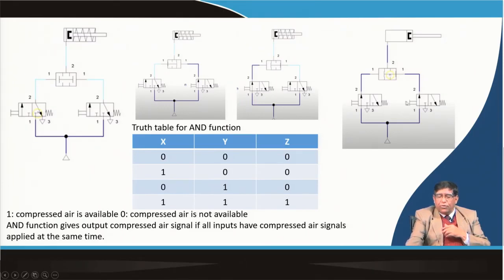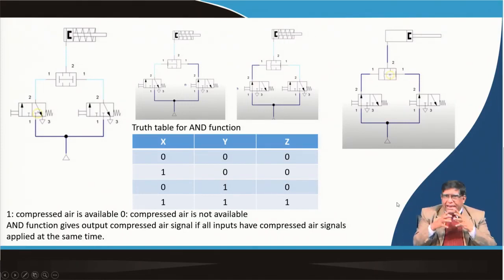But when the knobs of both these two valves are actuated or pressed, then you can get this air, and you can see this cylinder's actuator has now moved. So in any pneumatically powered system, this way you control the inner circuit by the valves. Here you can see the logic gate: when both are 0, Z will not be there, but only when both X and Y are working, then only Z is in the on condition.